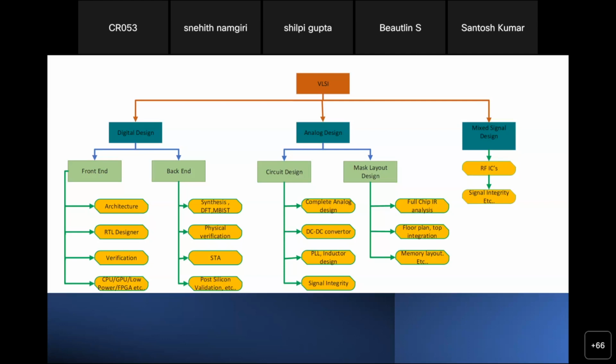Under physical design there are a lot of areas, because it goes through a lot of steps. Let's say you're transferring data and you have a clock, but your data is reaching and the clock is a bit delayed, so your clock and data are not matching. There is a timing requirement for any circuit because you want to achieve a speed, right? Speed means less time, which means there is a timing requirement. That's why you need STA engineers, physical verification engineers, and DFT, design for testing engineers.